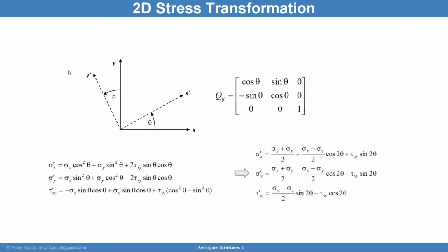Now, let's say I only have a rotation about the z-axis. You can use these equations fairly simply, and all you have to do now is calculate the direction cosines. When you do that, you get this equation here: cosine theta, sine theta, 0, minus sine theta, cosine theta, 0, 0, 0, and 1. This should be fairly simple to calculate based upon what we learned so far.